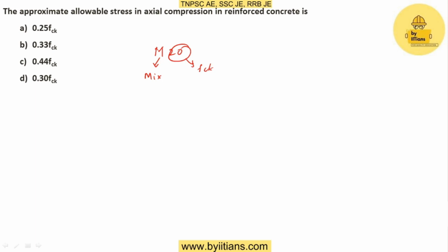Okay, this FCK value will be determined in the laboratory with the help of 3 sets of cube. Okay, 3 sets of cube having a size of 15 by 15 by 15